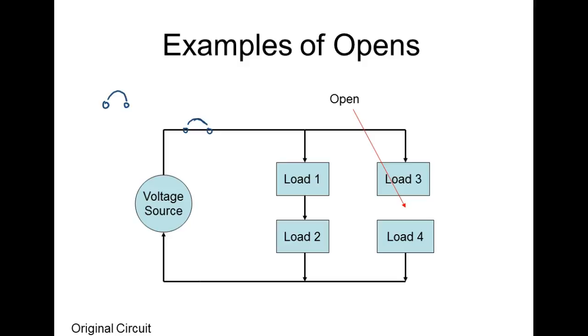When I was a kid, everybody had fuse boxes. My dad used to keep spare fuses in the house. If a fuse blew, he would have to go in there and do what? He'd wrap aluminum foil around it if he didn't have one. That was very dangerous. Now if I put a light switch, this is a series circuit, but if I put a switch, then the switch would be over here, right? A circuit breaker is in series or in line with everything that you're trying to run off that. In houses we call that a branch circuit.